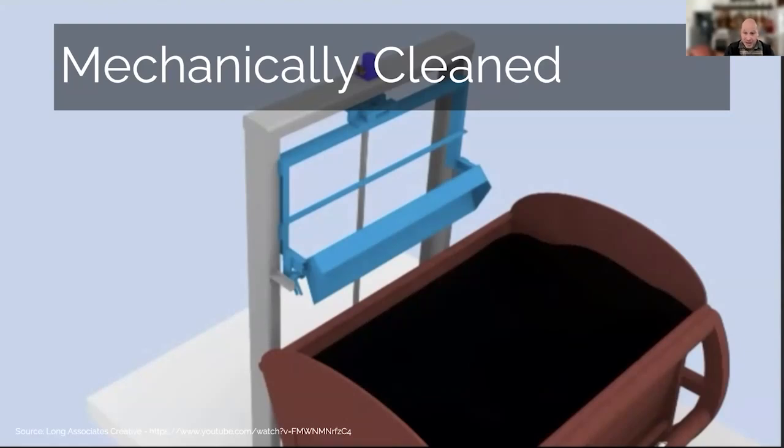But if your system doesn't have SOPs, or standard operating procedures, related to mechanical equipment, it's really important to develop some. We'll talk about those a little bit in later sessions, and you should also have daily inspections as well as weekly, monthly, quarterly, and annual maintenance routines to take care of this equipment, because it really is your front line of defense. And breakdowns here can have large negative effects on the treatment further down the line.